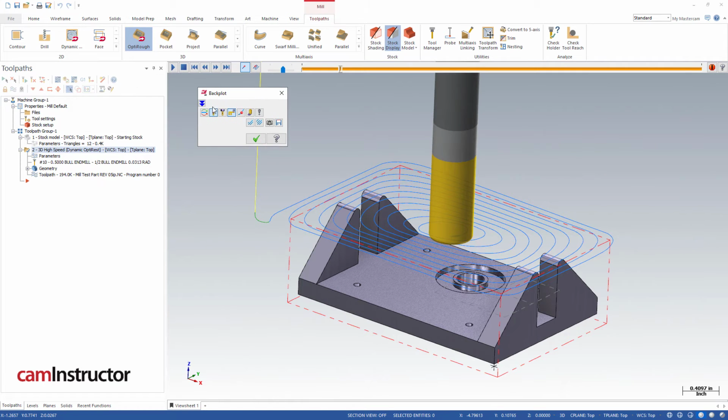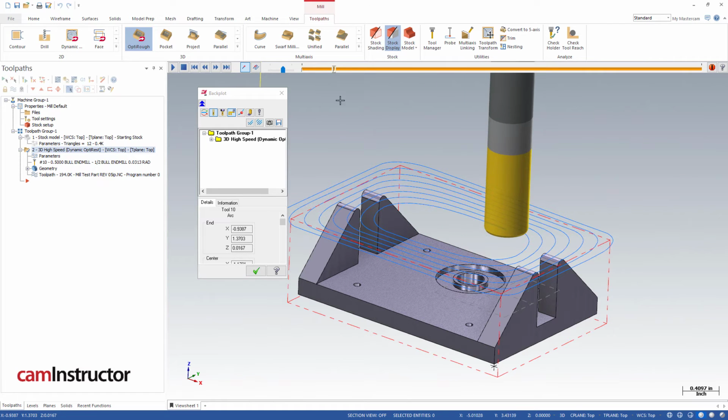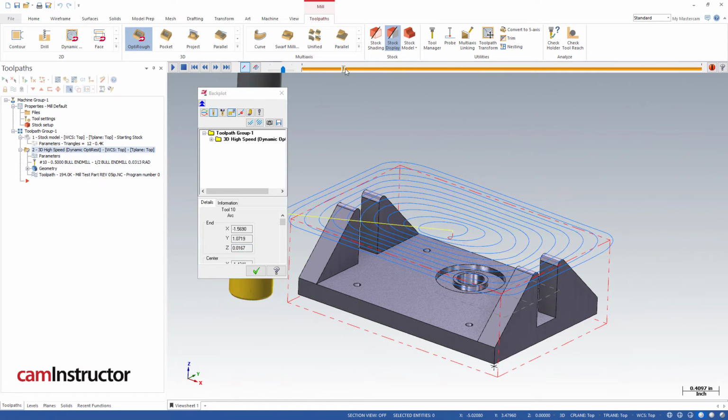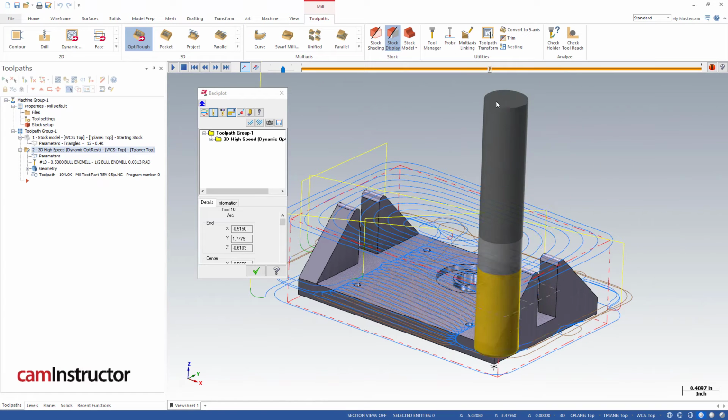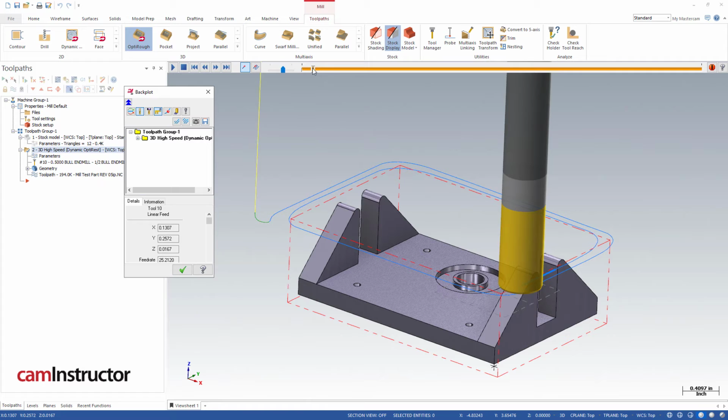So this thing right away, let me expand this out, is cutting at a value of positive 47.5. Oh, sorry, 16.7. I was looking at the retract values there. So we're at positive 0.167, and it's cutting all the way across the part. So not great. So what's going on there? That's problem number one that we need to deal with.